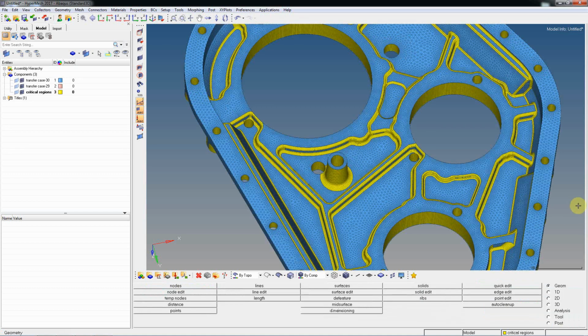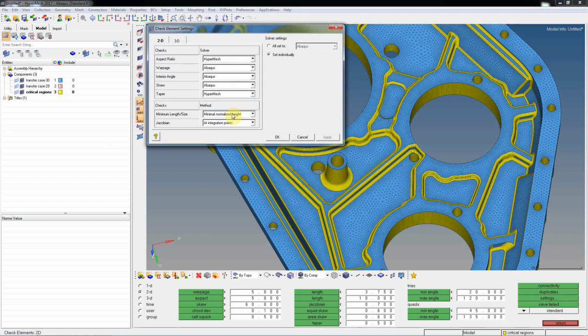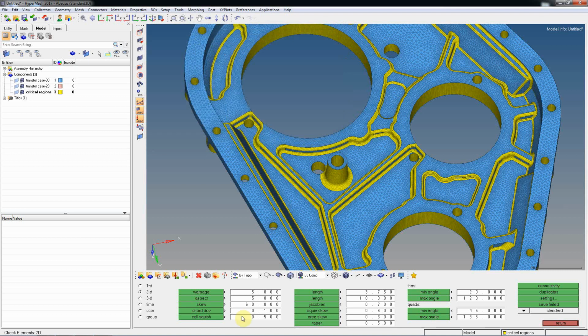Then what you need to do is check these qualities. Aspect ratio. Before you check aspect ratio, you can select shortest edge, just setting, done, and then you can check aspect ratio and skew, maintain 55, what I said. So no skew failed but aspect failed, and minimum and maximum angle, these are the elements failed. So these things you need to fix up. How exactly are you going to fix these things?